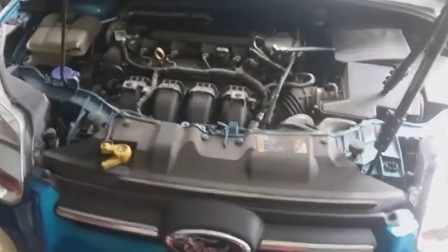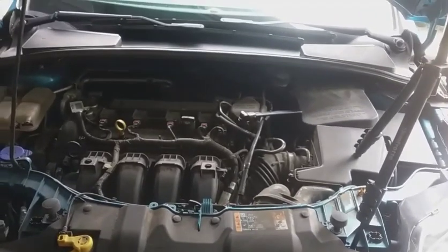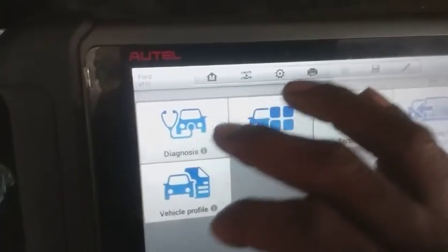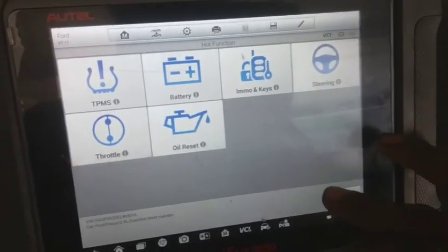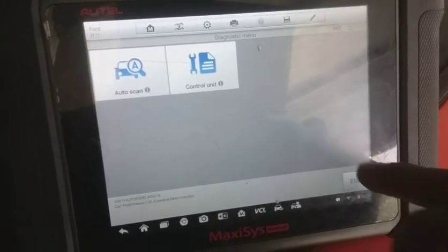The evap system operates off of removing those vapors and re-emitting them into the engine. And when it does that, it can burn off those vapors and help with the emissions and possibly fuel economy. If it creates a richer condition, it can lean out the actual fuel mixture depending on the load there.